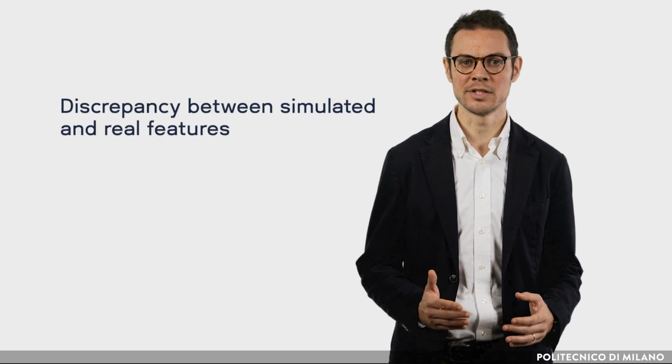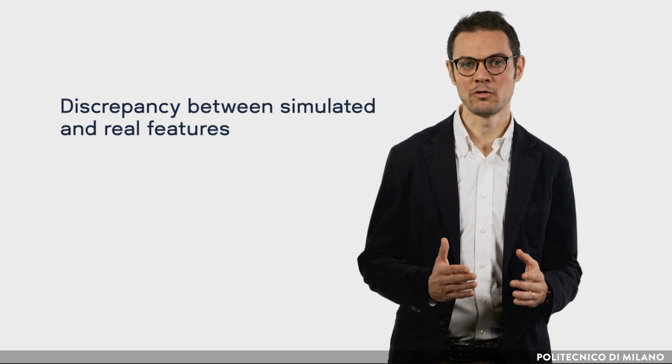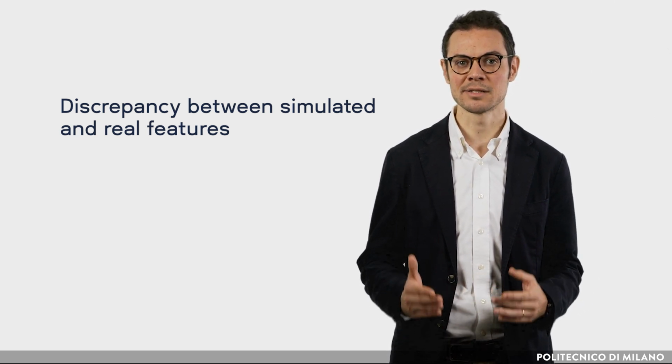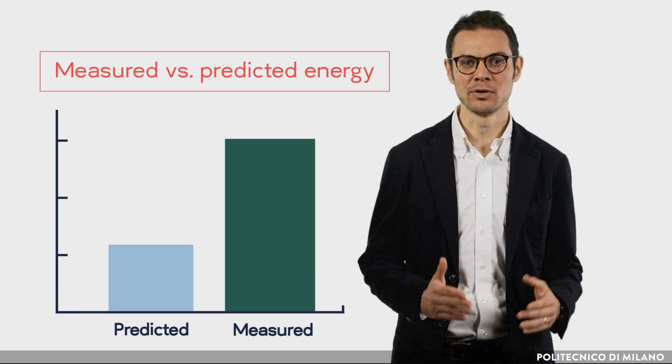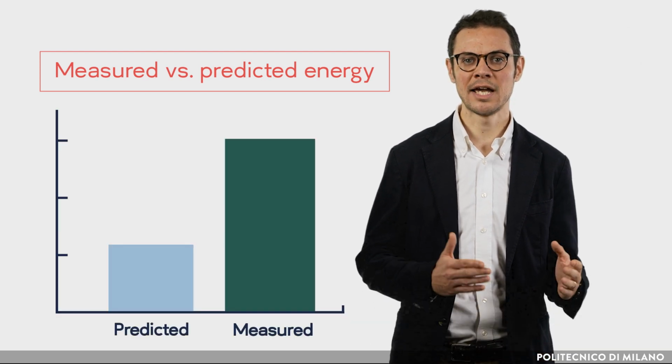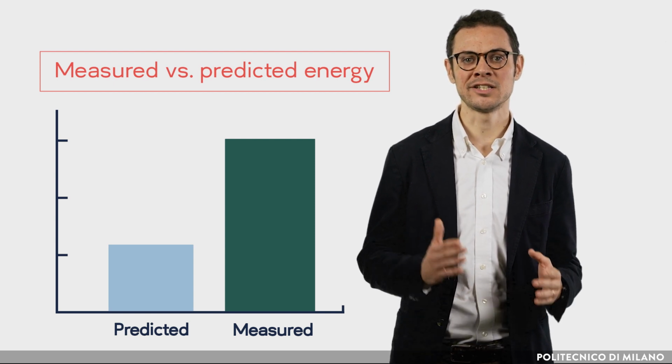Although building dynamic simulation tools are commonly recognized as a suitable way for accurately assessing the performance of buildings, in general, more or less large discrepancy between simulated and real features can still be observed, both for new or existing buildings. Moreover, the actual gap observed in many cases seems too wide to be acceptable. In fact, measured energy use can be as much as 2.5 times the predicted one.